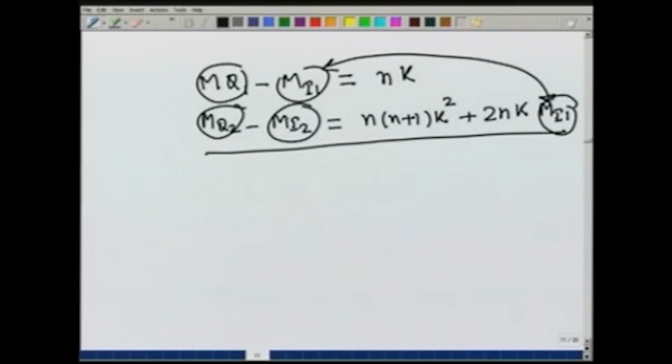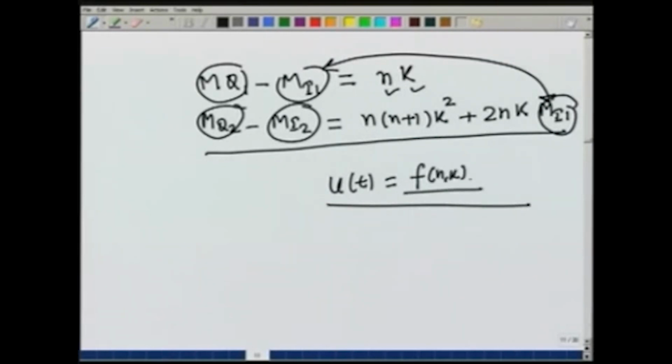So, if we have these 4 values known from an ERH and corresponding DRH, we can estimate the values of n and k, and once we have n and k, then we know that IUH ordinate is given by the gamma function, exponential, and all these. So, these two n and k are the parameters which will depend on the catchment and may be obtained from an available ERH and DRH value. So, the IUH which we have discussed just now takes care of any non-uniformity in the rainfall, where we cannot approximate it by constant intensity over certain duration.